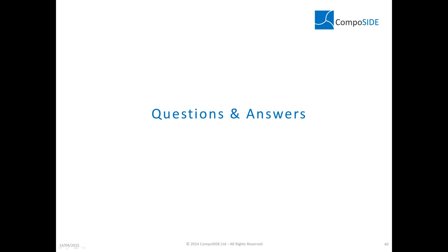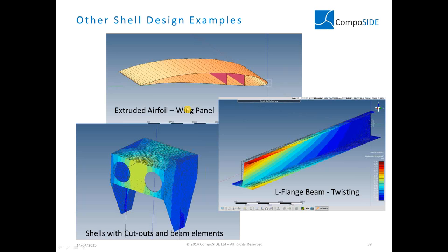Okay, the question about importing CAD geometry. Yeah, you can import the DXF files on a sketch, then extrude, for example, and create shells. Or for the beam design, you can also base your section design on an imported DXF file. We are working to extend this import functionality with a STEP files import or an IGES, STEP import. This is going to be available later in the later releases. Yeah, we are working on that. It's going to come.